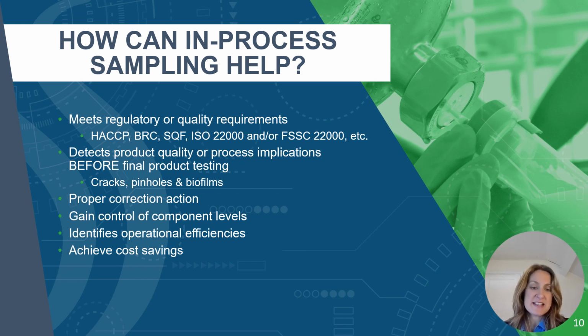Looking at operational efficiencies, if you're taking good sample data, it allows you to understand: are you running for the right amount of time? Can you push your process to add another hour to the very end? What is going on with your pasteurizer after the first 3-4 hours? Are you seeing changes in that bacteria level? Are you seeing bacteria build up over time? What is going through your process? Without good sample data between pieces of equipment, you really have no idea how that process changes over time, and whether you can modify it, extend it, or need to shorten it.